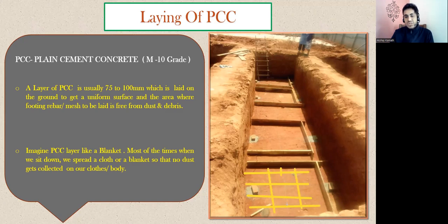This reinforcement mesh, that is the rebar, you're directly exposing it to the soil. In the soil, there may be some foreign materials, or let us say there may be sulfates, chlorides and so on. Again, that will come in contact with the rebar and the concrete, right? There may be a reaction between them. As a result, there might be corrosion in the rebar, and if there is corrosion in the rebar, the durability is going to come down. I don't want all that to happen.